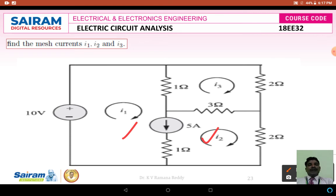We write the current equation this way because this 5 amperes current source is in loop 1, so we give priority to I1 and write the current equation as I1 minus I2 is equal to 5 amperes. That is the first current equation.